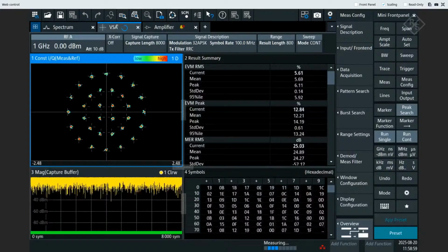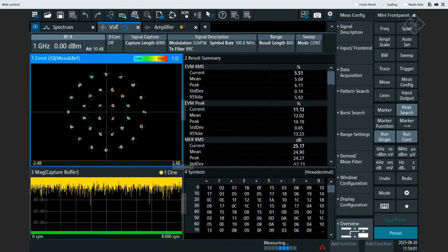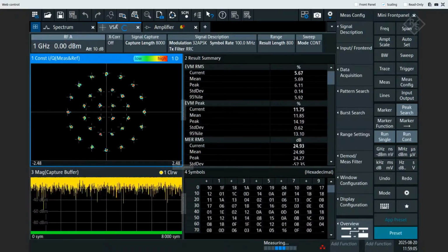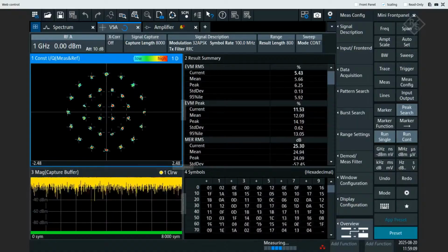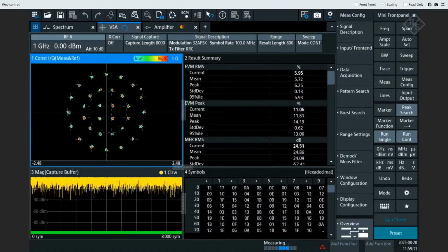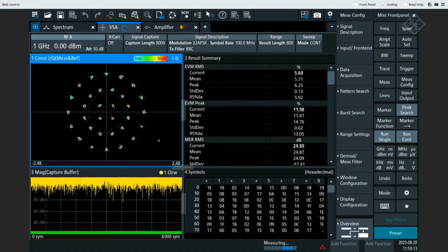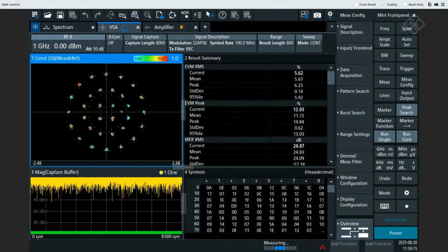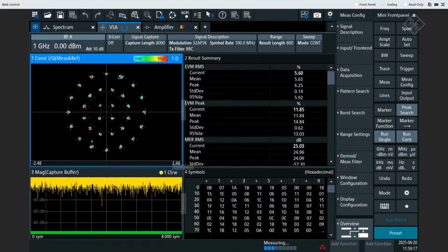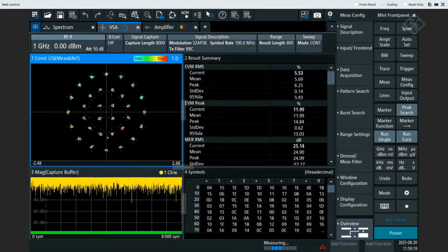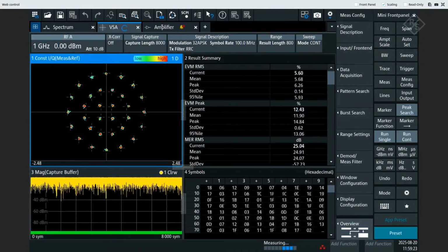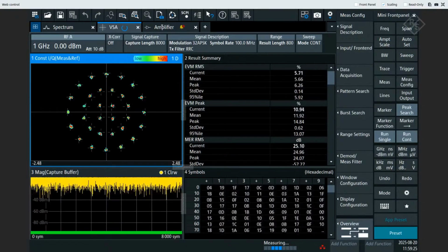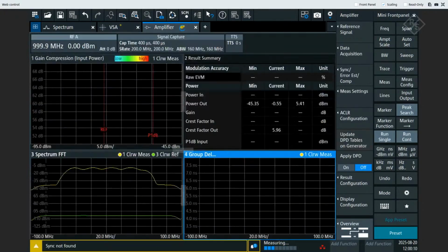Before we enter the device characterization, we'll have a quick look at the constellation diagram of the signal under investigation. For that, I'm using the VSA single carrier demodulation option, just to show you that the signal we are using here is a standard compliant DVB-S2 signal with a 32 APSK modulation on it. With that, let's have a closer look at the LNB itself.